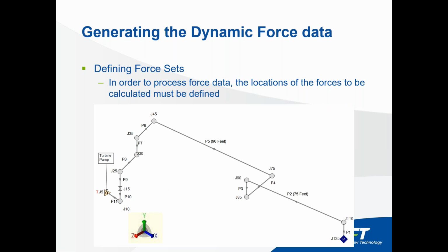Before I go on, I would like to explain what we're going to do. We're going to analyze the forces in the longest pipes. It's not that the other pipes are not important, but since the pressure wave does not last long in each one of them, the imbalance force does not pass very fast, and so generally the longest pipes are a major concern for the pipe stress engineers.